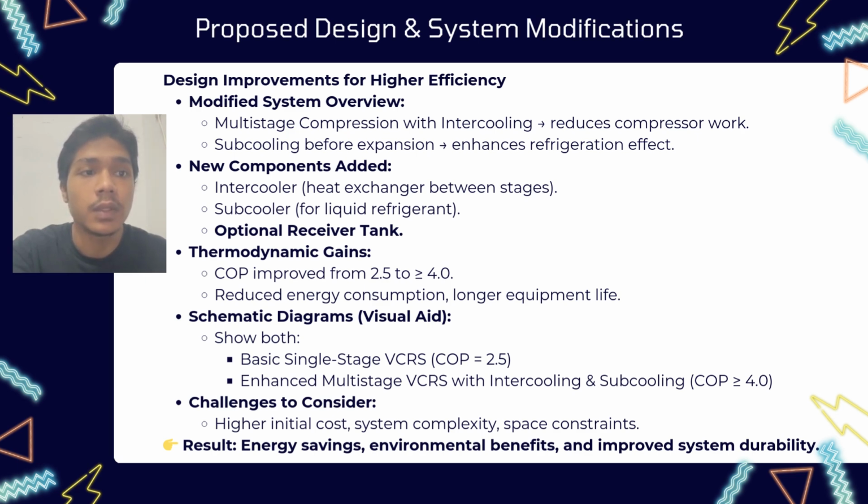The intercooler reduces the refrigerant temperature before the second compression stage, which lowers the overall work required and improves system efficiency.